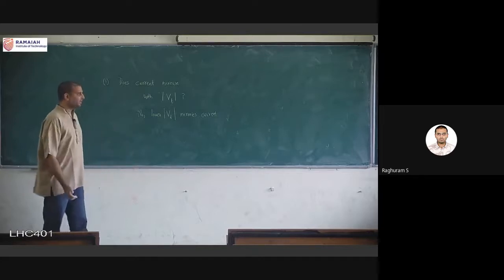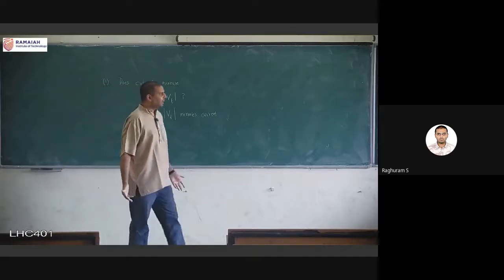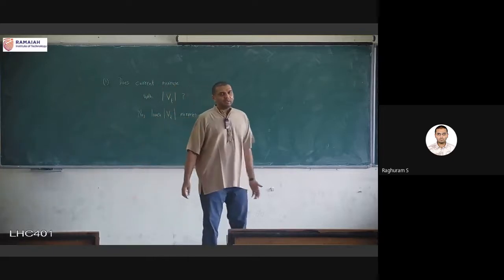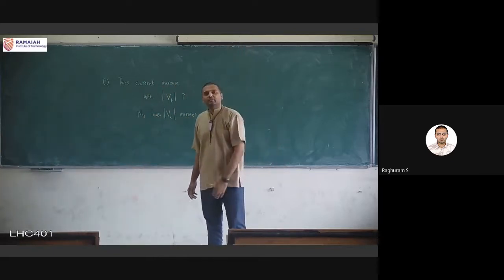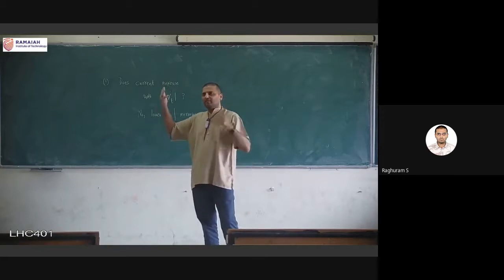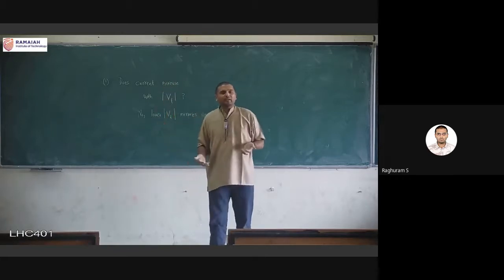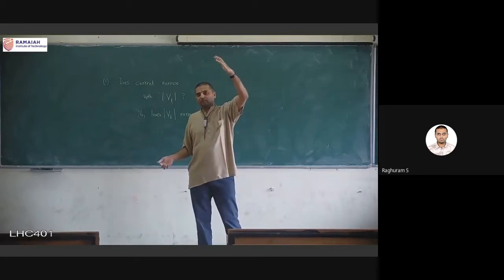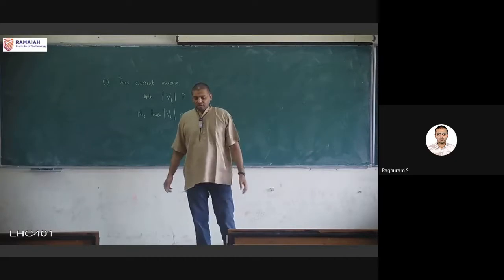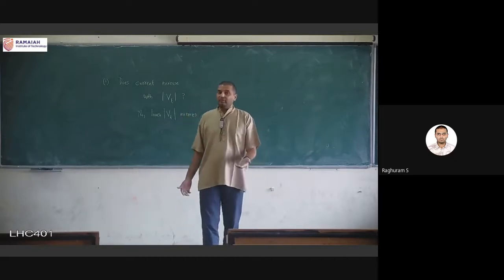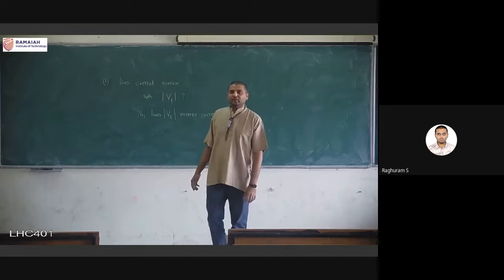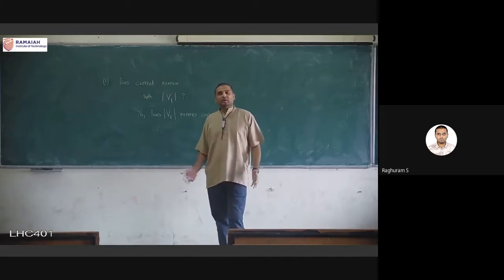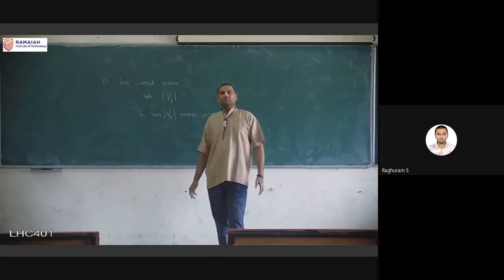Then you might ask me, what is the limit? Why can't I keep every transistor I make at the maximum possible value? W by L has some maximum value. We saw one example where in 180 nanometer technology, the maximum W is 50 micro and L is 180 nanometer. Why can't I keep everything at maximum value? What is the possible bottleneck there? It's a valid question. Why do I ever have to reduce it? Keep all the transistors at the maximum performance.